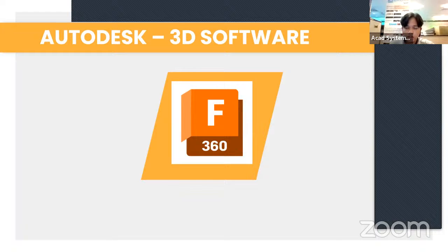What could be the difference between them? Let's focus on the difference in creating parts and assembling models between these two software. For Inventor, to create an assembly, we need to create separate files for our components or parts, and then we can combine them into one assembly, which could lead to consuming a large amount of storage by having many files and folders on your PC.